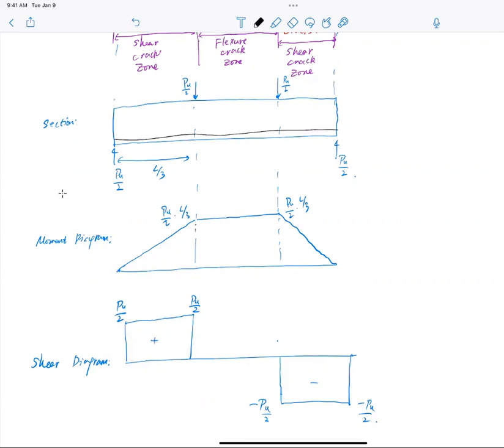But now note that in the middle section there's a higher moment, and it tapers down to 0 as you go into the support. So I may add more to the middle. And that's my tensile reinforcement, or we call it flexure reinforcement, what you have learned so far.